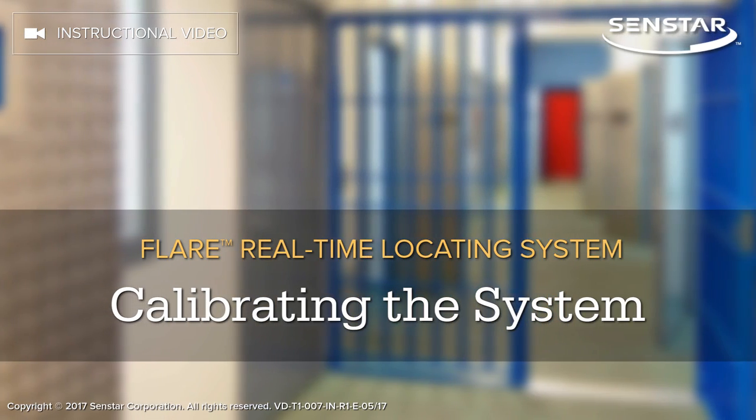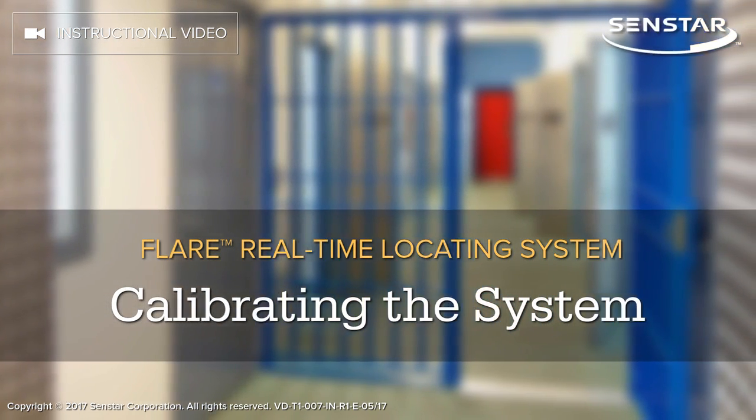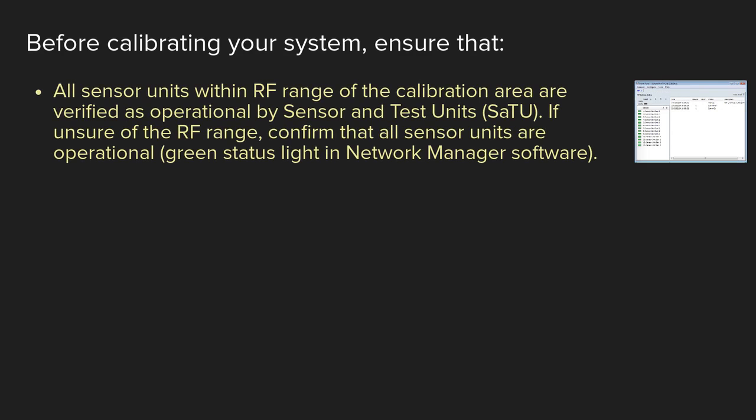This video explains how to calibrate and test a flare system. Before calibrating your system, ensure that all sensor units within RF range of the calibration area are verified as operational by Sensor and Test Units, or SATU. If unsure of the RF range, confirm that all sensor units are operational by a green status light in Network